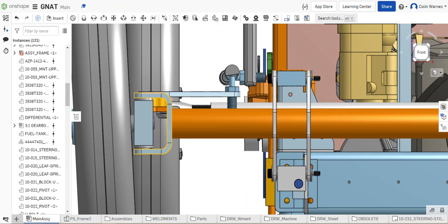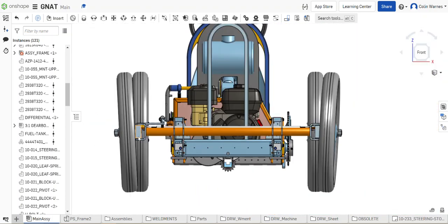My pivots are vertical, and if you draw the imaginary kingpin line down, you'll see that I have a very small kingpin offset. That's the distance from the center of the wheel to the centerline of the kingpin, where those two points meet the ground. The goal is to make that distance as short as possible. The small kingpin offset gives you almost a power steering effect.